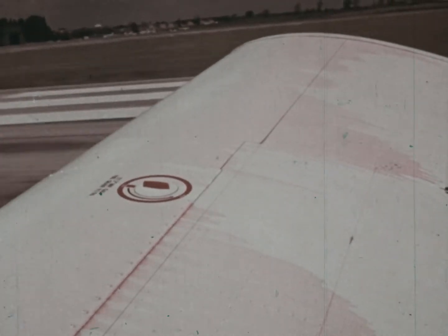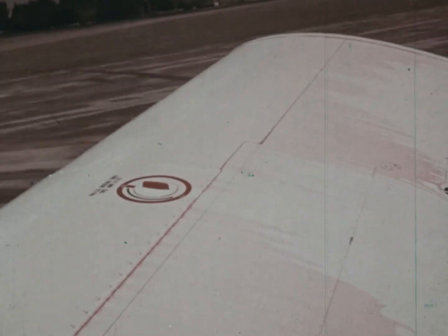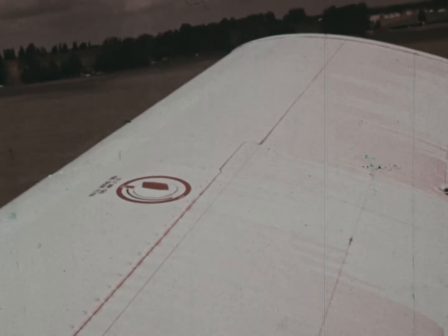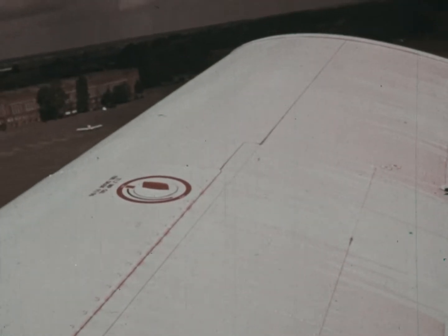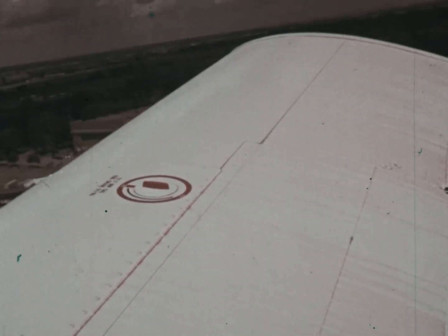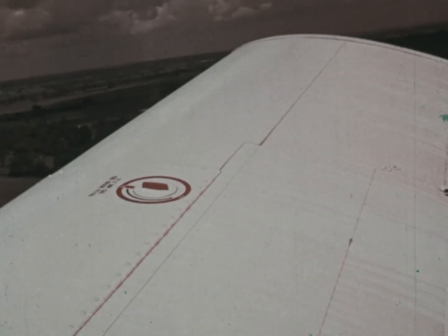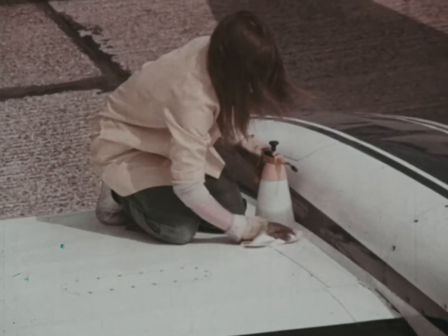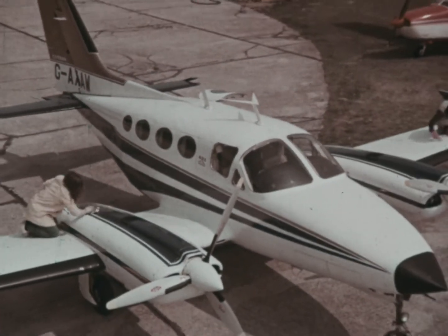As the outer layers gradually let go, we are left with a thin, slow-moving film of liquid at the surface itself. It is this clinging of the so-called boundary layer to the surfaces of the airplane that enables the pressure changes around the wing to give us lift. Pressure changes that also produce drag. Lift and drag are thus inseparable, but the drag component can be reduced, both by clean design and by keeping the airplane clean and polished, thus increasing its efficiency.